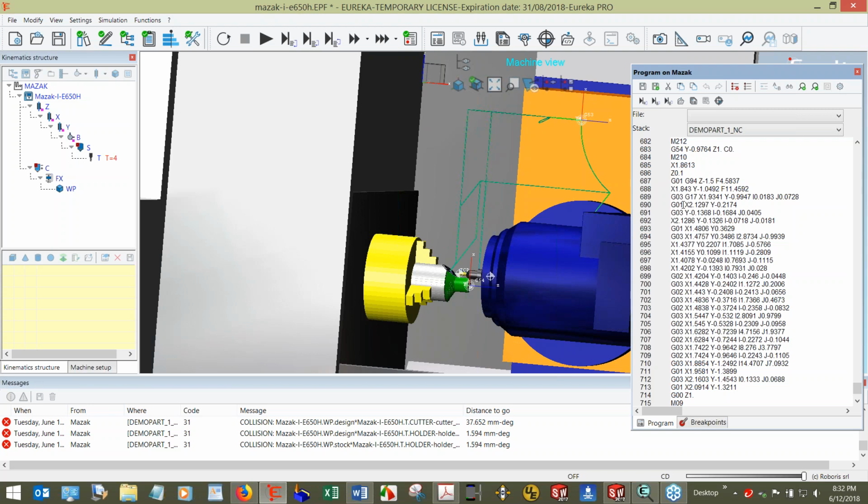Now with true machine control operations, we have a better opportunity to create that motion in the CAM tree and give a better sense of what is happening. We still have to go through a post-processor to generate the G-code. So there is always the potential that if a post-processor has not been proven out correctly, then the movement at the machine may not represent exactly the movement that took place inside the internal machine simulation.